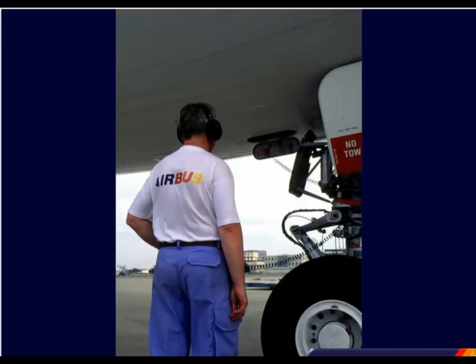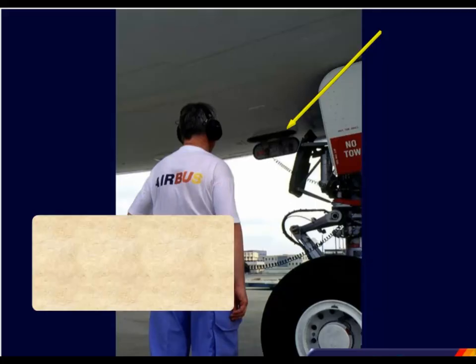Let's look for a moment at the outside of the aircraft to see the only item associated with the electrical system on the walk-around. You should check that the ground electrical power door is closed, if not required. You have finished normal operation A. We will continue with normal operation B.